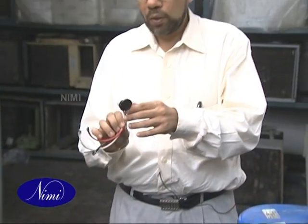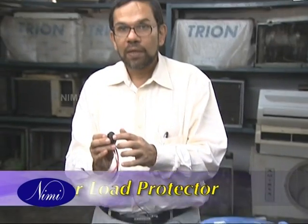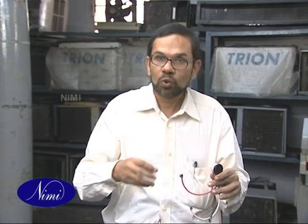Now we'll talk about the overload protector. This overload protector is fixed on the body of the compressor, and it senses the temperature when the compressor gets too hot. It has a bimetal fixed within it. This bimetal, sensing too much heat, opens, and when it opens, it cuts the circuit to the compressor. So the purpose of the overload protector, like the name says, is to cut out the compressor when there is too much current or too much heat from the compressor.